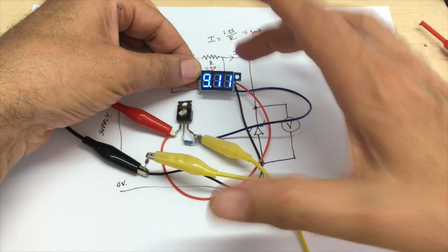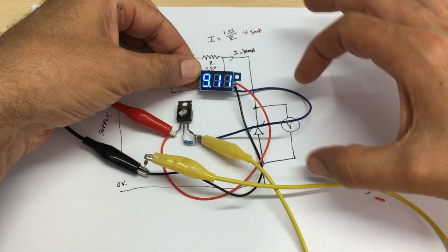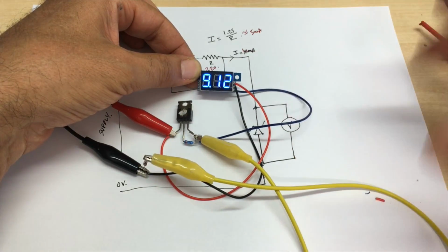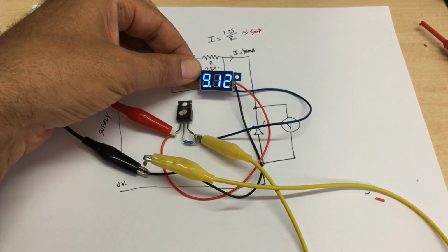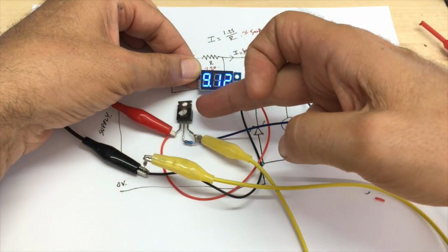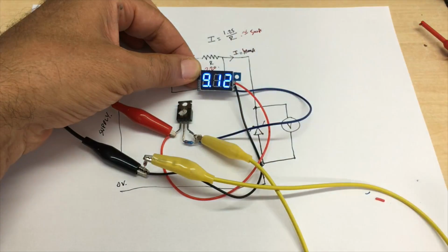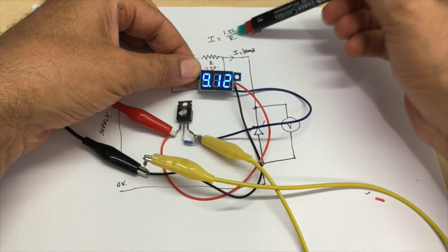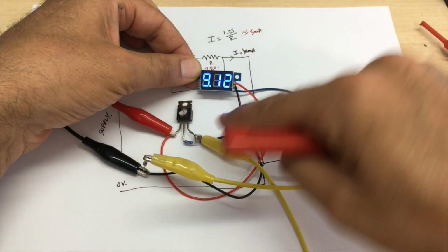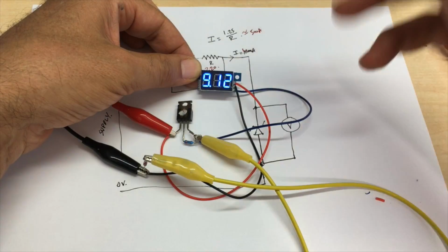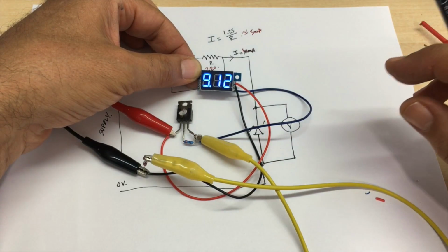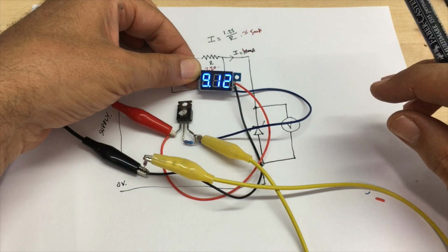Basically, I've replaced the voltmeter. In the case of the circuit here, this voltmeter, instead of being the multimeter, is now this internal, very cheap, very simple digital voltmeter. The resistor calculation is done away with by using the LM317 constant current source. At the moment, it is set for 5 milliamps, but I can change that resistor to make it whatever I want. Now, the only other thing is, what do I need to make this self-standing?